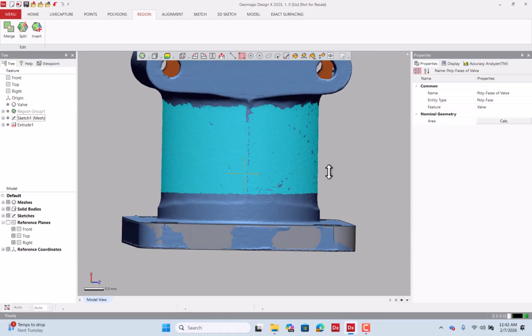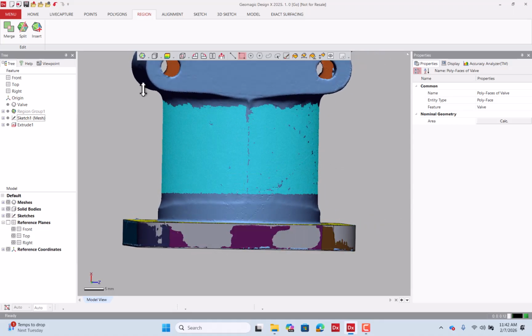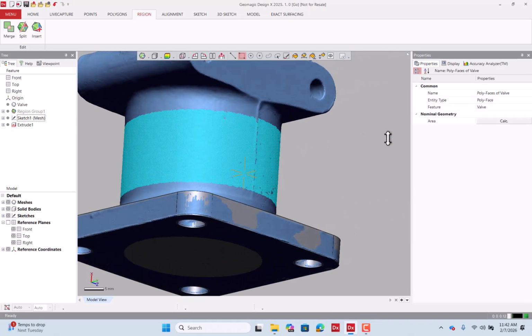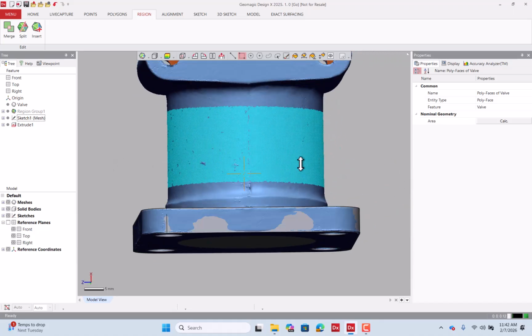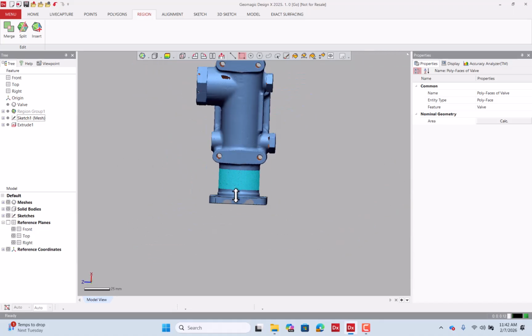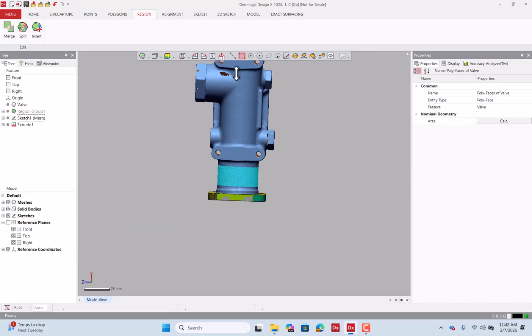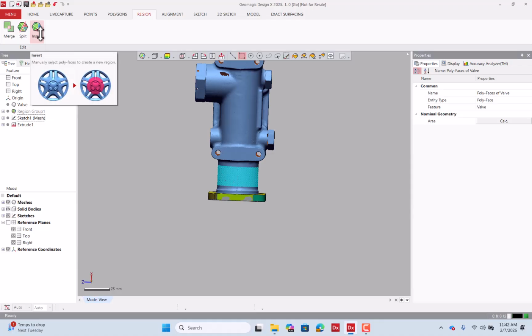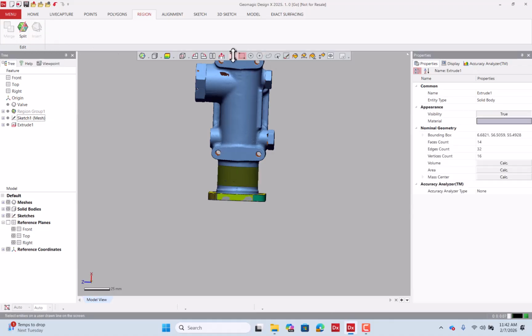And even in the upper side, you can remove this area of filleting. So I'm holding Control and I'm just keeping the area which I feel really confident about. Now I can say insert here to add this particular selection as a region. So I'm clicking on insert, and then I can go to the line selection mode and click on that region and see that it's a cylinder.